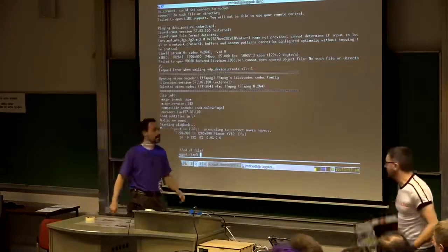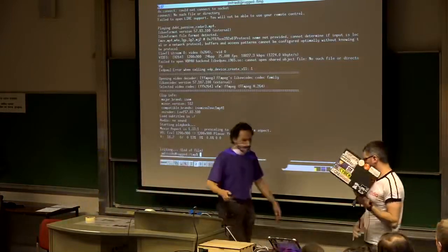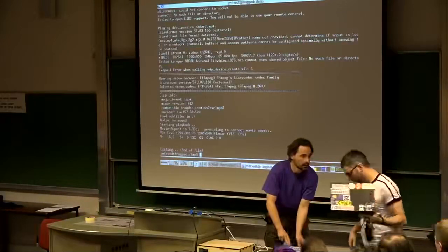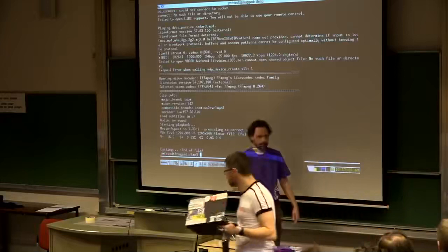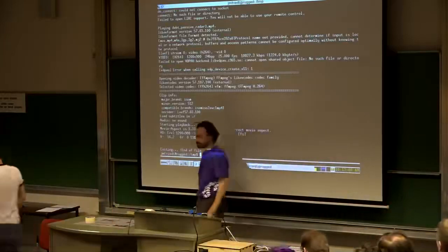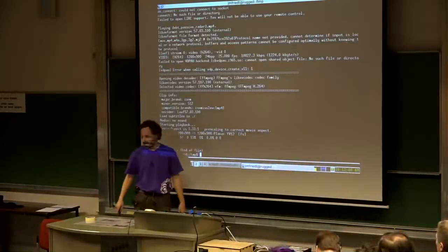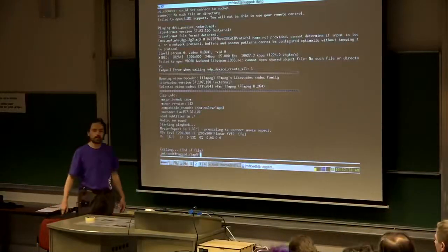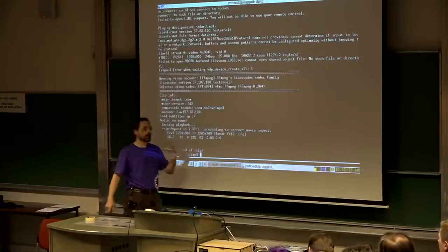Maybe Marcus? DVB-T comes with very nice receivers with channel equalization and stuff. So is it possible to actually receive the bits that are in the DVB-T signal and reconstruct the original signal to increase the signal-to-noise ratio? So the question is whether we can regenerate the signal by just decoding DVB-T and regenerating the carrier.